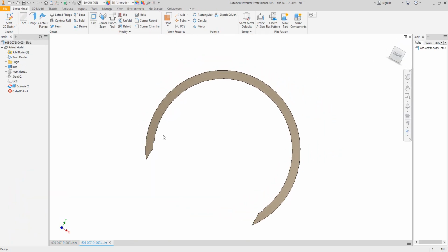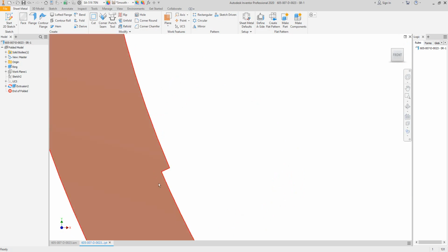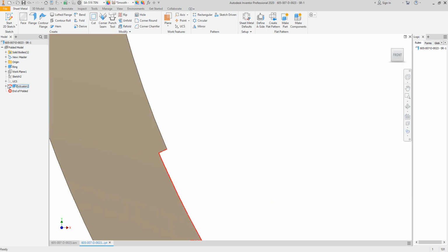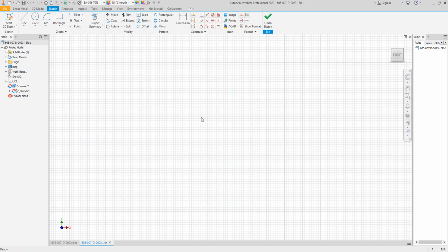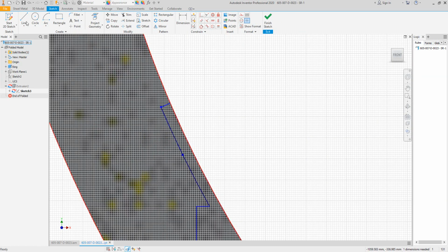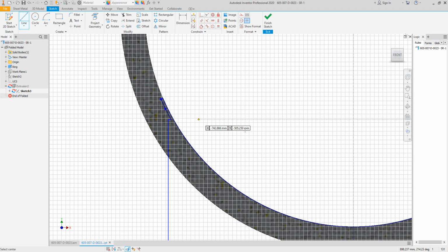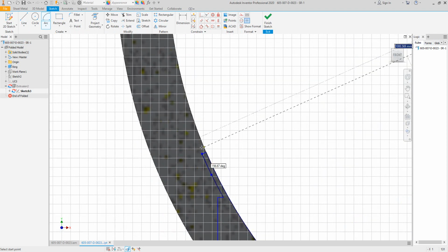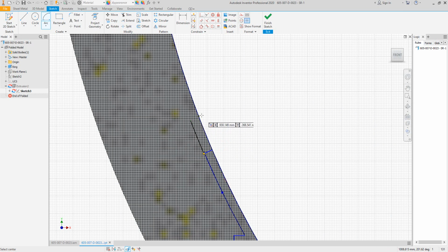And if you would like to make a modification like a notch or something like that, you can do it easily on the sketch itself. For example, if you would like to increase this cut a little bit, you can increase the arc length from here to there, okay, and add another closed area, and you can make a cut for it.